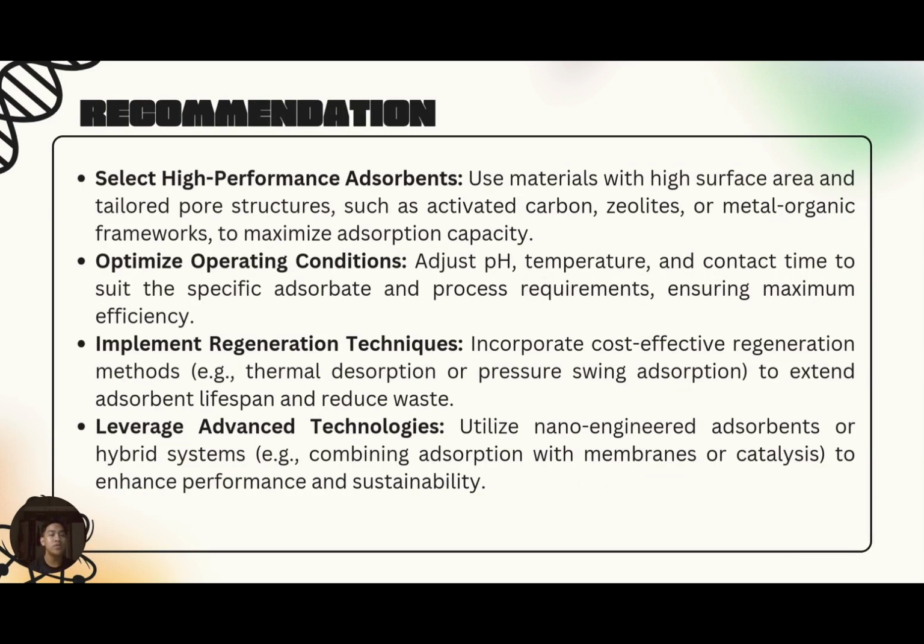The next one is recommendations to get better results. The first is high-performance adsorbents. We use materials that have a high surface area, like activated carbon, zeolites, or metal-organic frameworks (MOF). Next, we must optimize operating conditions, like adjusting the pH or the temperature.